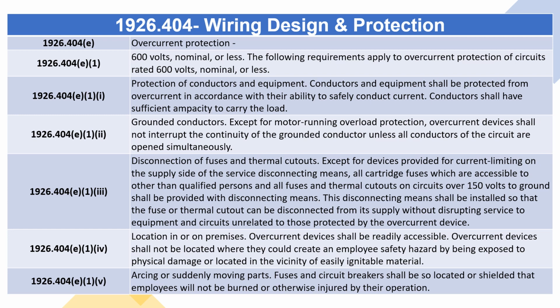1926.404(e)(1)(ii) Grounded conductors. Except for motor running overload protection, overcurrent devices shall not interrupt the continuity of the grounded conductor unless all conductors of the circuit are open simultaneously.